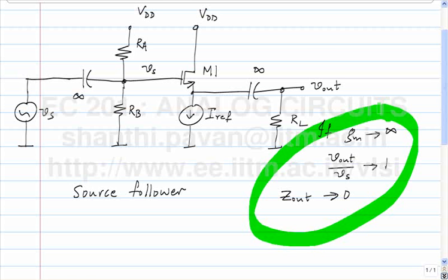The incremental gain will decrease dramatically, which means that the output, which was supposed to be a nice clean sine wave, now has presumably the top or the bottom chopped off.